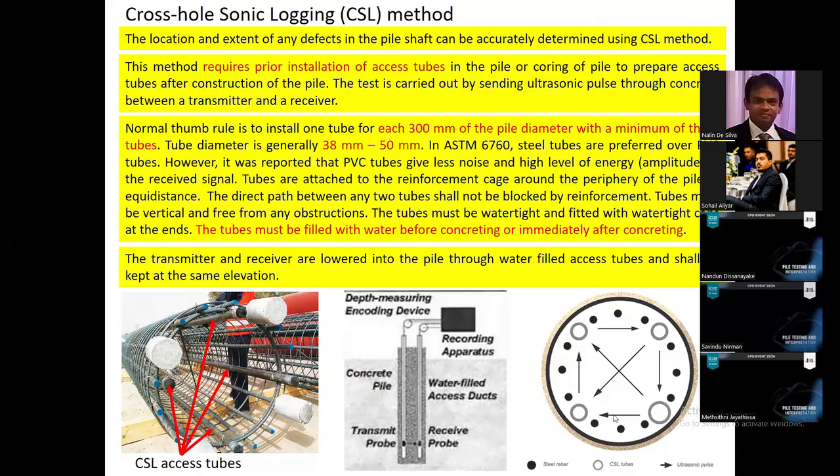We lower the receiver and the transmitter to the bottom of the tube and start lifting them at the same time, maintaining the same elevation, right? While sending waves, both the transmitter and the receiver are slowly lifted. And this test can be conducted in this manner.